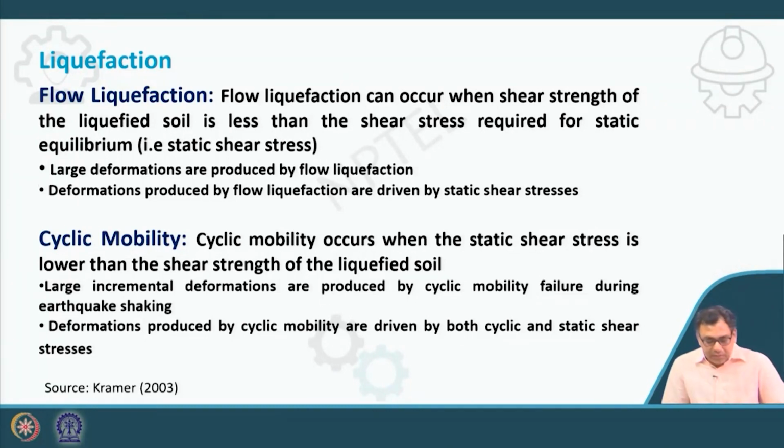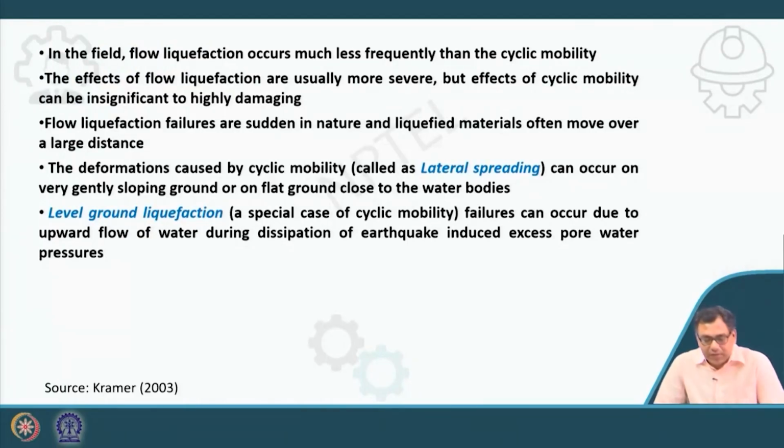Now, in the field, flow liquefaction occurs much less frequently than cyclic mobility, but the effects of flow liquefaction are usually more severe, while the effects of cyclic mobility can range from insignificant to highly damaging.